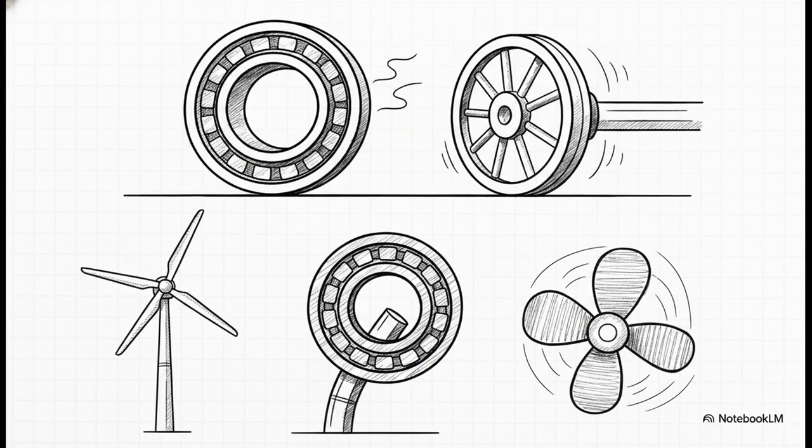Cylindrical roller bearings are optimized for high radial loads and speeds, super common in train traction motors. And what's really amazing is the NU-type configuration. It intentionally has separated rings that let the shaft float axially. This brilliantly accommodates thermal shaft growth when a gearbox heats up.